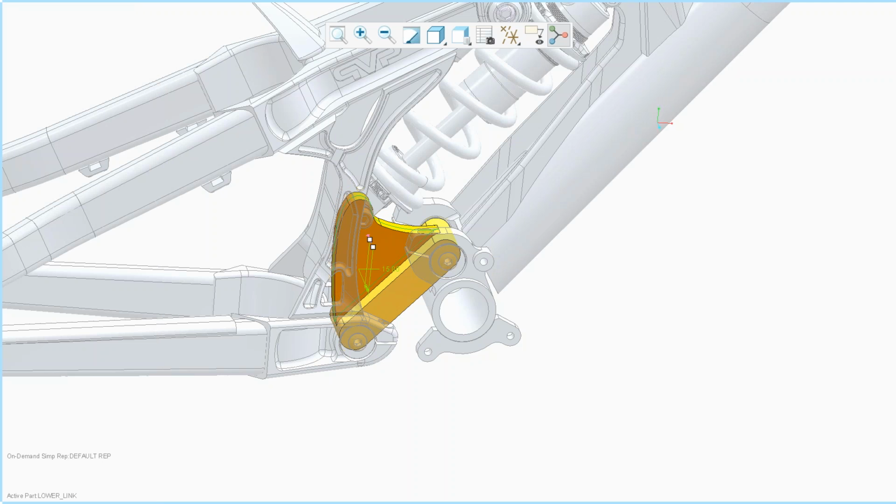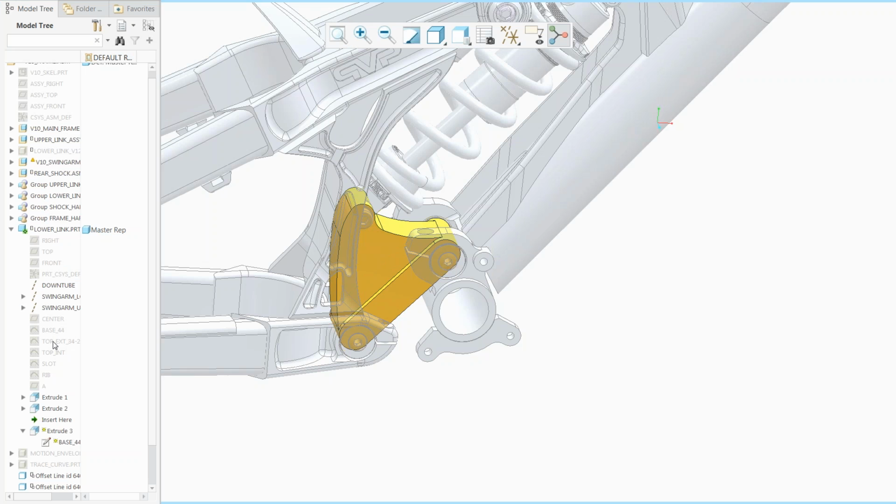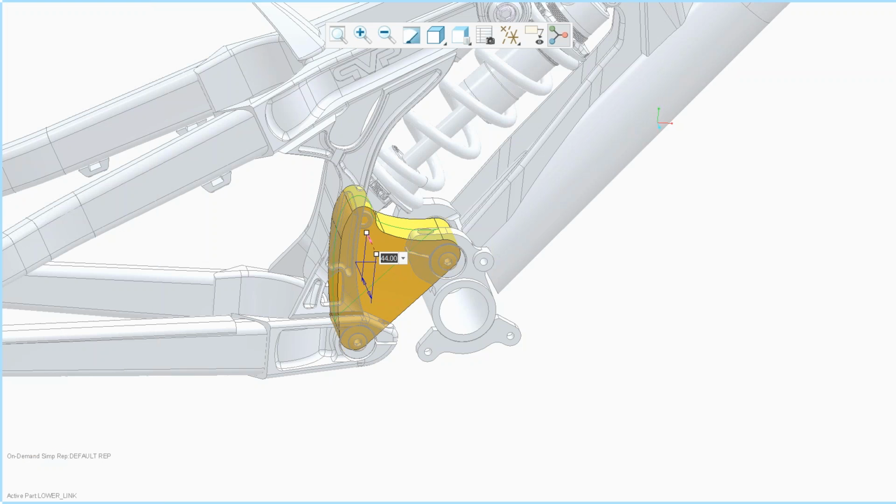And when I copy-paste with a different sketch, I get to maybe assign, so I'm repeating the feature using an alternate sketch. So you can see several tips here. I'm focusing on the design at the same time reusing that design. So again, let me do another paste. But this time, I'm going to use the same sketch again, but to remove material, right there.